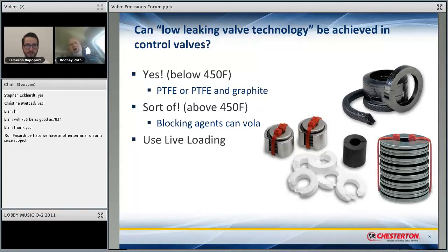They don't know what component or components are causing that emission, except for mass leakers. Because if your background reading is a perfect 100, then you can go up to 105 parts per million before you're considered to have busted the 100 ppm leak definition.